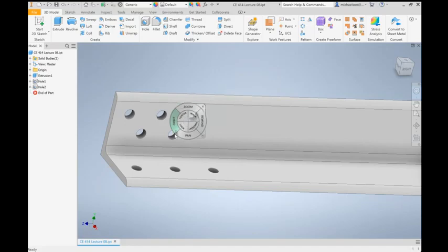So all the failure paths are going to be the ones that follow this lead line and leave the bolts intact. And so for this connection, that was really only 2 paths. That was just this straight perpendicular path in front of these two, and the zigzag like that. Did that answer it?